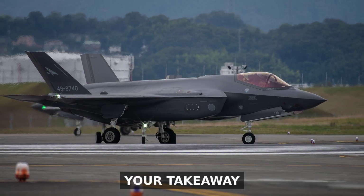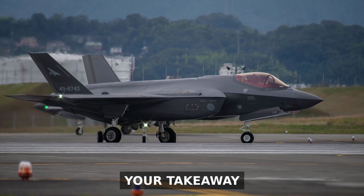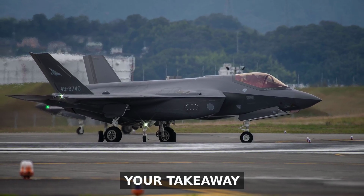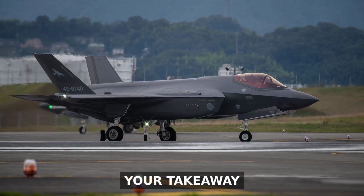Your takeaway: always know your angle of attack. Fly coordinated turns. Manage your airspeed in the pattern. And if the stall warning sounds, reduce the angle of attack immediately.